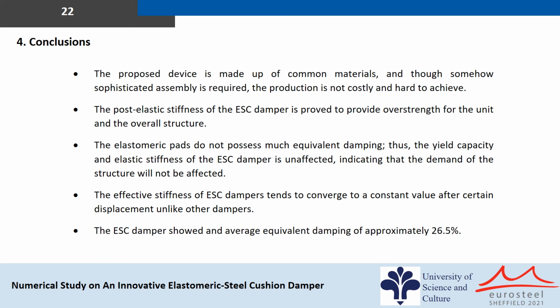The elastomeric pads do not possess much damping, thus the yield capacity and elastic stiffness of the ESC damper are unaffected, indicating that the demand of the structure will not be affected. The effective stiffness of ESC dampers tends to converge to a constant value after a certain displacement, unlike other dampers. And finally, the ESC dampers showed an average equivalent damping of approximately 27%.